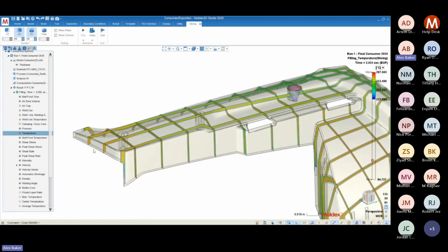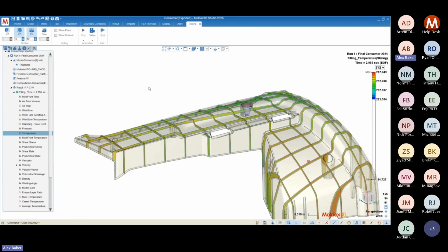This here is what we call the shear effect. The energy released into the mold is what we call the cooling effect. Which of these effects is dominant will dictate which area of our part is the hottest. You can see that in this case, the end of fill is the hottest, so the shear effect dominated. If the temperature decreased over the length of fill, which admittedly is the more common scenario, then we could say that this was a cooling dominated flow.